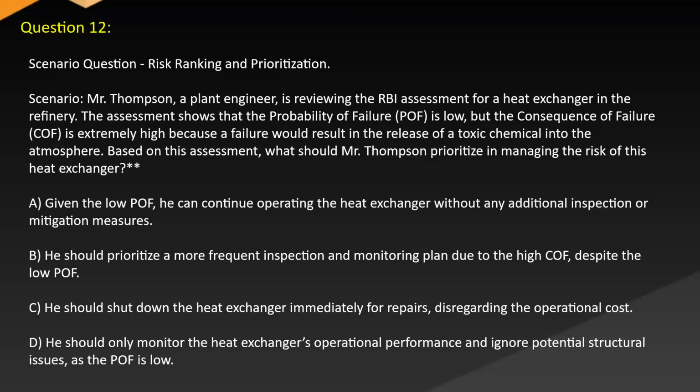A. Given the low POF, he can continue operating the heat exchanger without any additional inspection or mitigation measures. B. He should prioritize a more frequent inspection and monitoring plan due to the high COF despite the low POF. C. He should shut down the heat exchanger immediately for repairs, disregarding the operational cost. D. He should only monitor the heat exchanger's operational performance and ignore potential structural issues, as the POF is low.